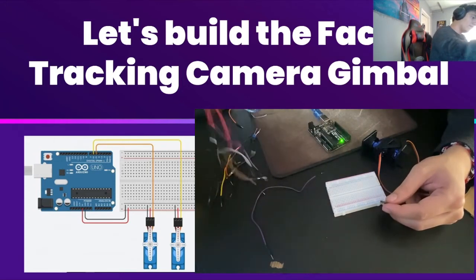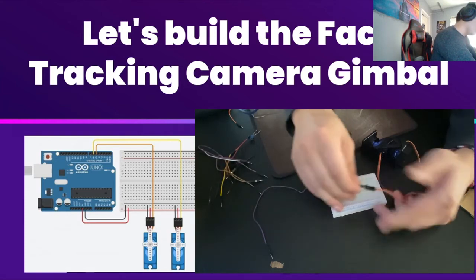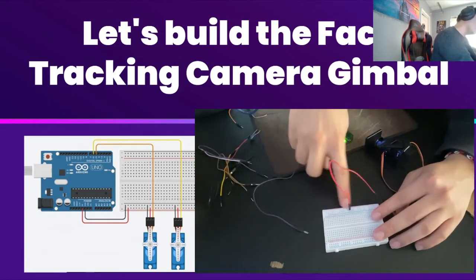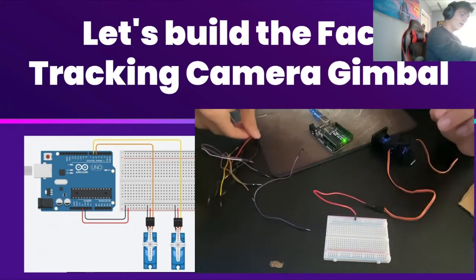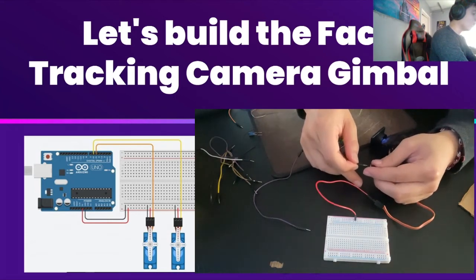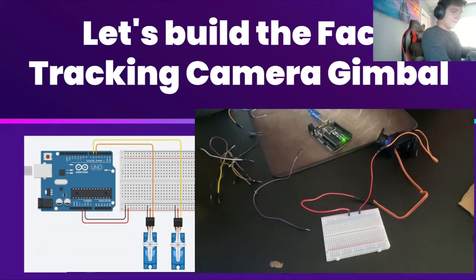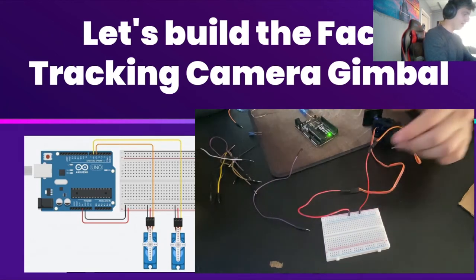Go ahead and get your red wires. If you have any red wires, go ahead and connect it to the middle pin, which is the power pin. Like in the diagram, we're going to connect it to the positive terminal trail that connects all these together. So essentially, we can just connect one source of 5 volts to that one connection, and it would power everything that we have connected to it. So we have the power cable connected to the breadboard.